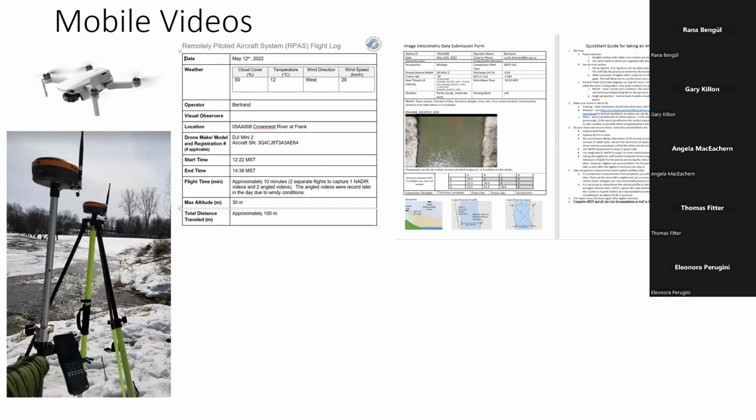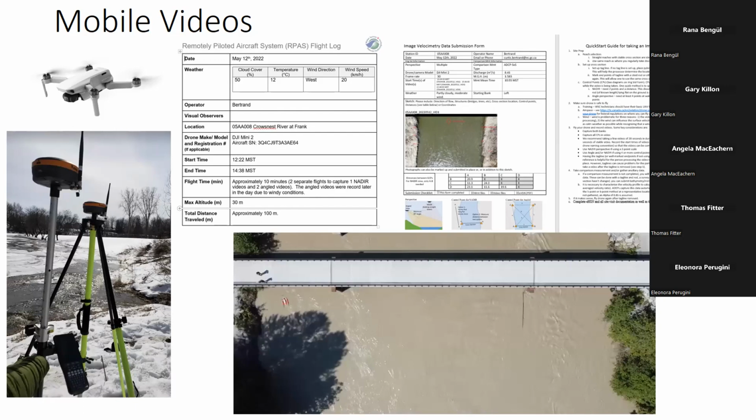So it's been a cost-effective way to use equipment that we've already got. And then to date, we've captured 37 measurements. So those are at least 37 times when at least one drone video was captured, and then a comparison measurement was captured with either an ADCP or a flow tracker, depending on the river, or salt dilution, actually.